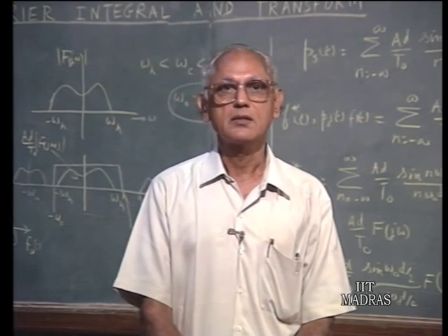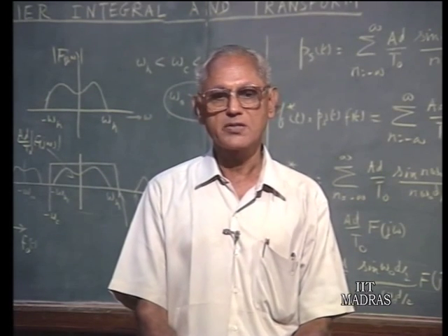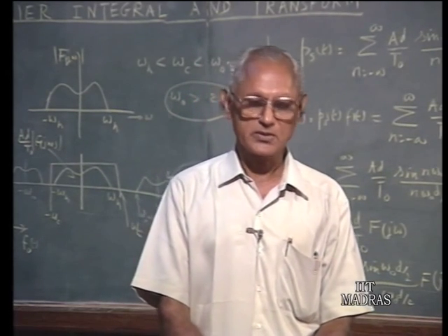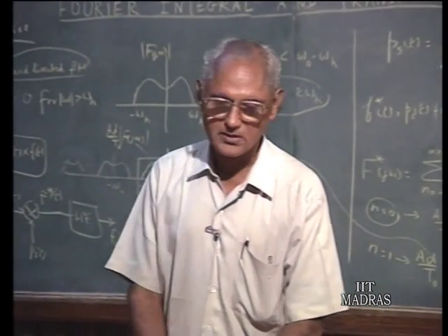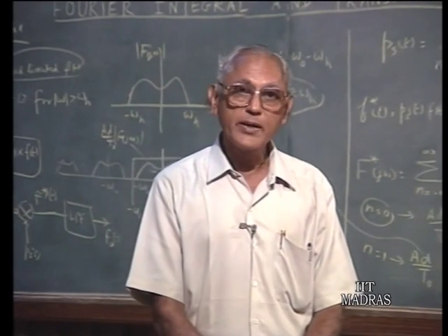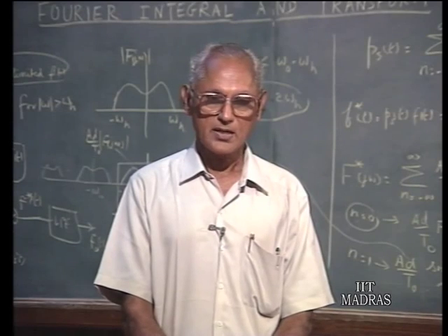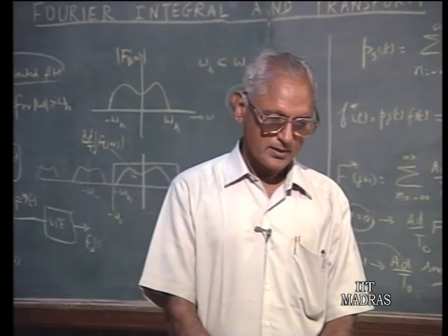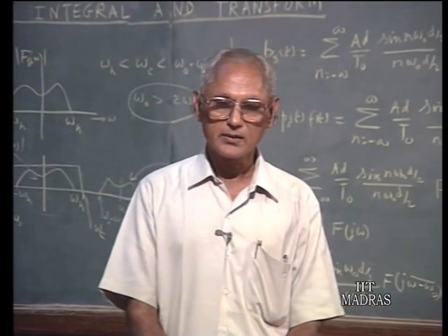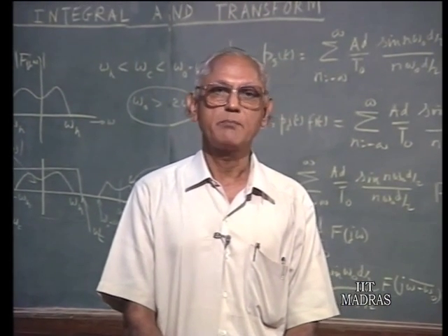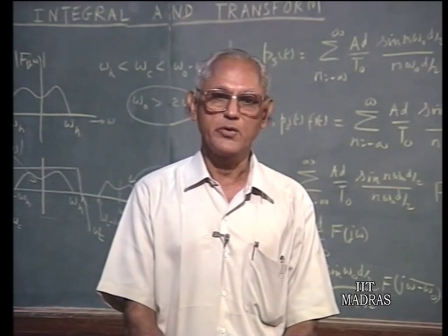When I say summation, it is actually the integration that is being done, because these are all a continuous band of frequencies, but the principle is the same. Summation is essentially an integration. Integration is essentially a summation. Now, it is this fact that transient behavior of networks and systems can be analyzed on the basis of steady state sinusoidal theory that places this Fourier transform method and Fourier theory in an important place in communication engineering.